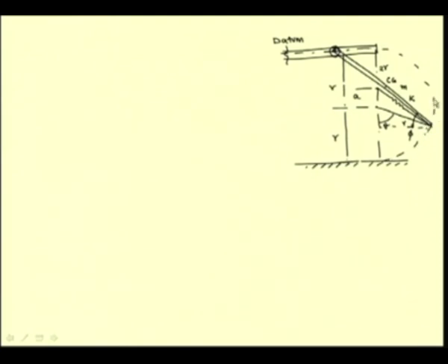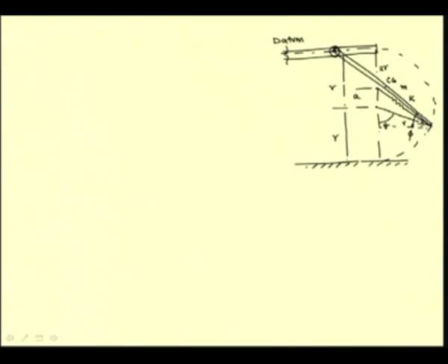This dotted line shows the locus traced by this end of the door as the door is lifted. So this is the completely opened position, and this represents the closed position of the garage door. And we have two sets of such springs, one on each side to support the door. We are interested to know the stability of the equilibrium of this door in the closed position.